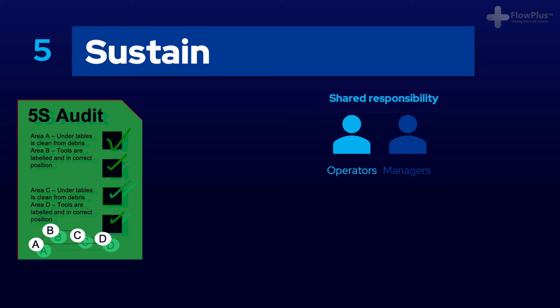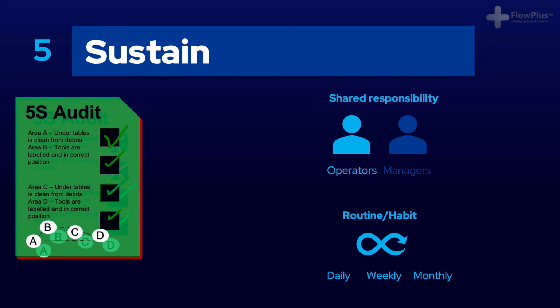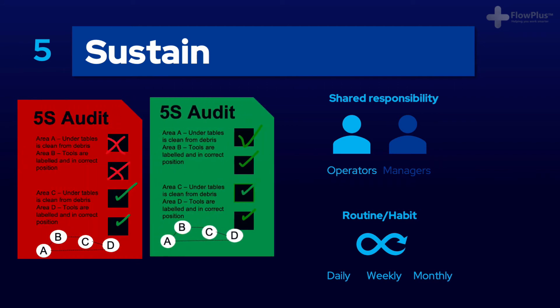These audits, in practice, take the form of a single A5 sheet of paper with the same questions written on both sides. By using simple ticks and crosses, each question can be answered. If any answer across the entire audit card is a cross, then the audit should be filled in on the red side of the card. If all the answers are a tick and the 5S standard is being upheld, then the ticks are all drawn on the green side of the card.